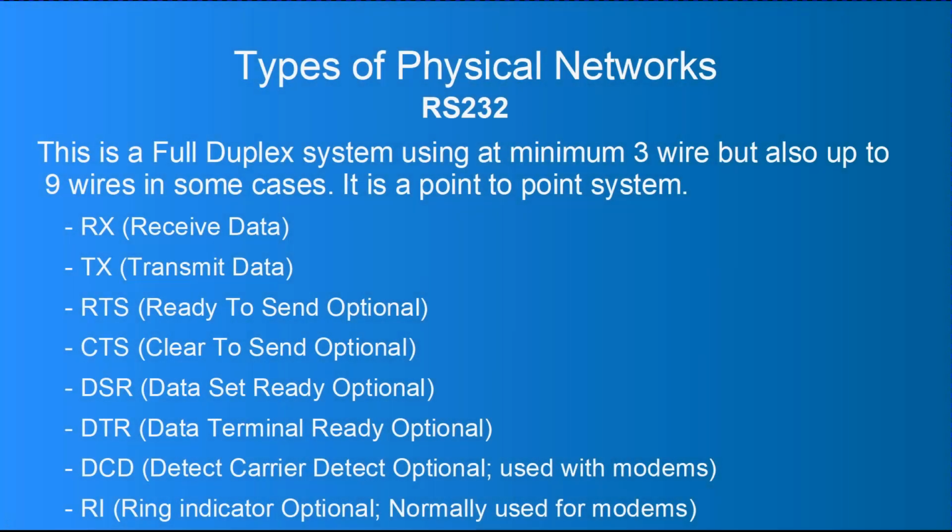So the RS232 doesn't have a long range. It's around about the 10 meter mark. Once you get over 10 meters, it starts to suffer terribly from interference. And so it's usually just a connection between an end device and your computer at a very close range. I haven't seen many cables for modems and the like that are more than a meter.